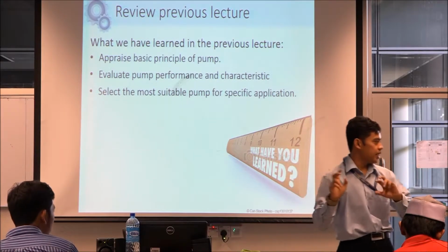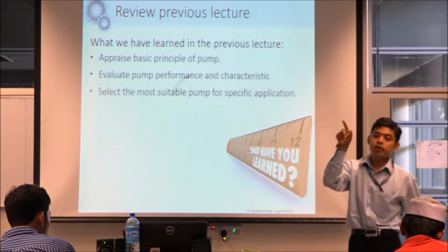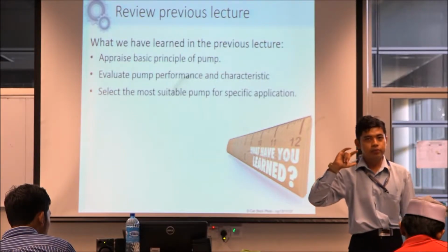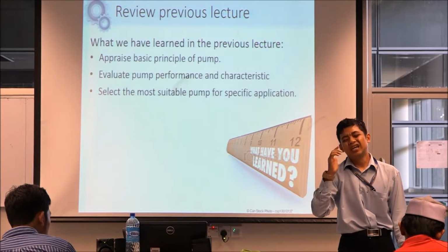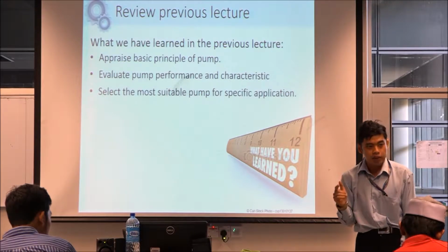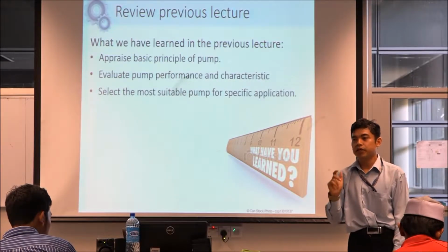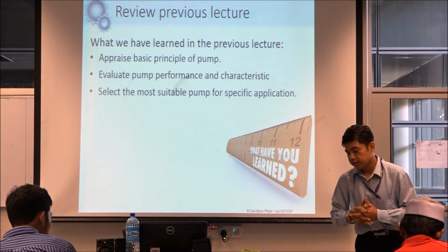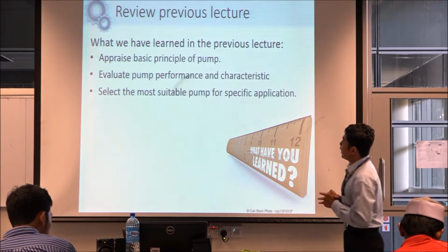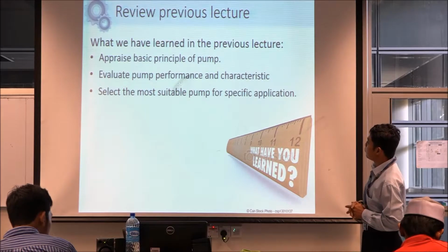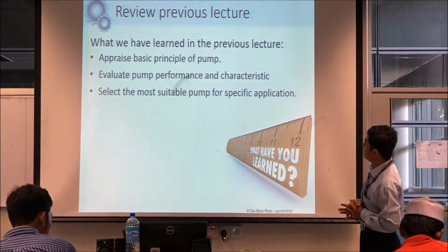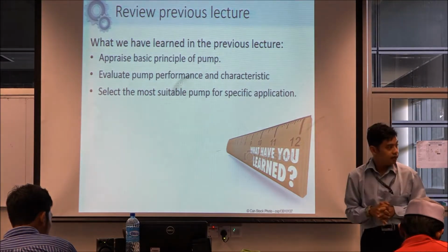When you get your HS and HP, you can calculate your W water, or water horsepower. When you get water horsepower divided by the efficiency of the pump, you get your shaft input. Okay? And then evaluate pump performance and characteristic. That one we have done.